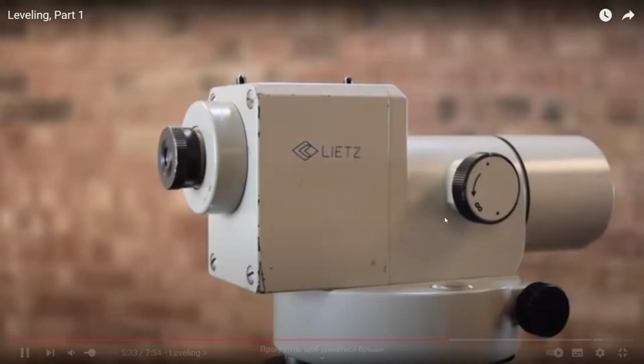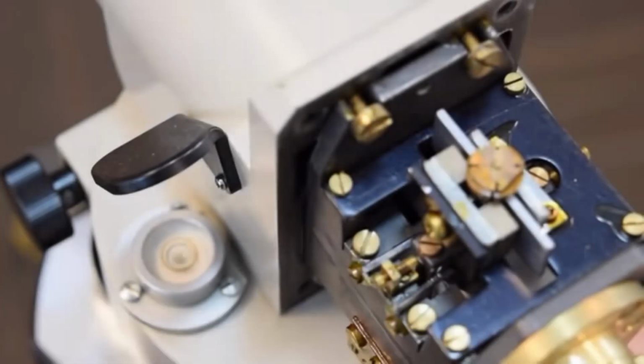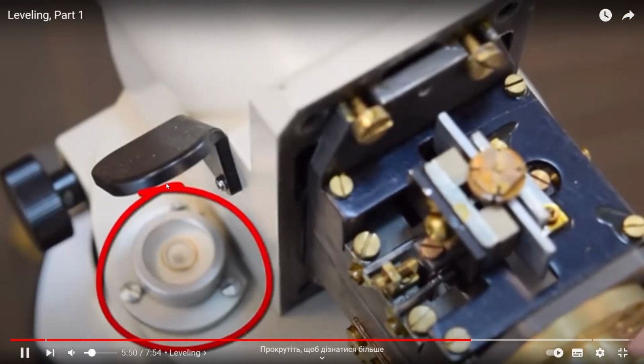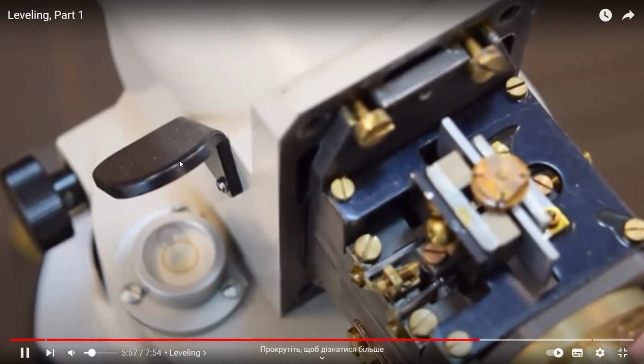Introduced in the 1950s, the automatic level contains a set of tiny mirrors that move automatically in response to gravity, ensuring that the instrument's line of sight is perfectly level. If the instrument settles during use, this automatic compensator simultaneously adjusts the line of sight through the mirror, keeping it in the horizontal plane.